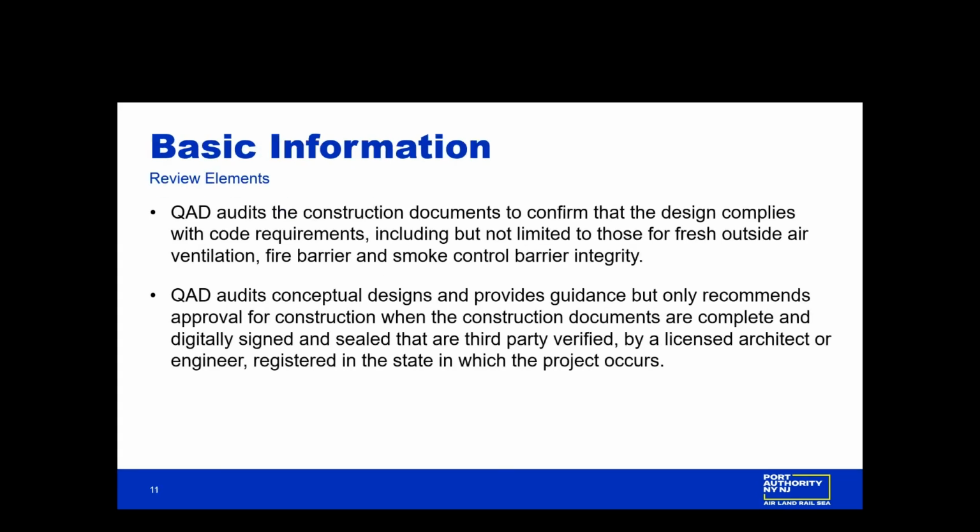Some basic information. Review elements when QAD audits the construction documents to confirm that the design complies with code requirements, including but not limited to those for, say, fresh ventilation air, fire barrier, and smoke control barrier integrity. QAD also audits the conceptual designs and provides guidance, but only recommends approval for construction when the construction documents are complete and then digitally signed and sealed and third-party verified by a licensed architect or engineer registered in the state in which the project occurs. Next slide.